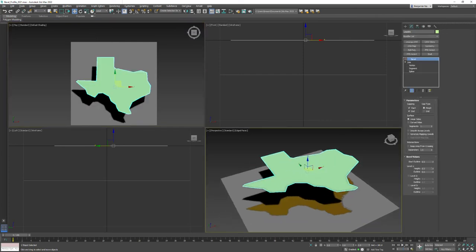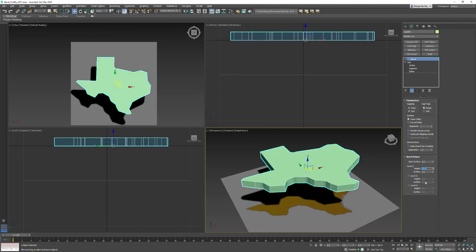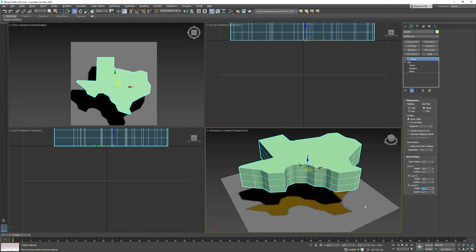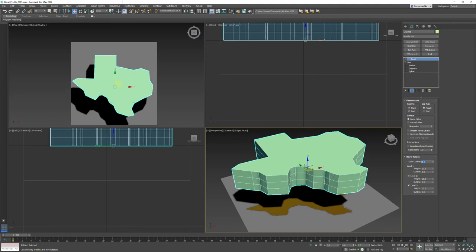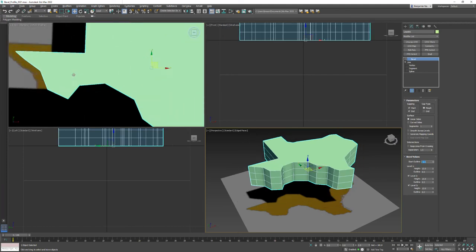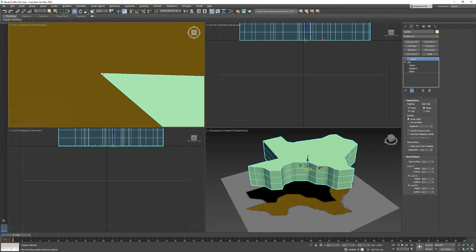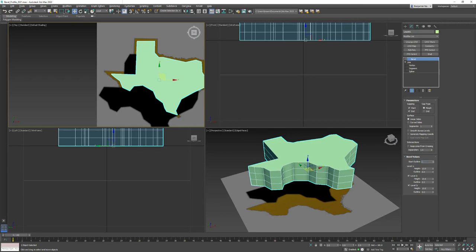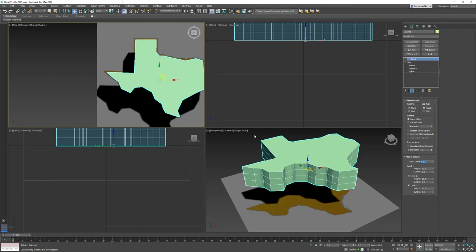Bevel allows you, think of it like this, you have 3 different values, or 3 different types of extrude. So I could say 10, 10, and 10. Now the reason that you have those is because you also have this starting outline. So if I set my starting outline to like 5, you see how everything pushes out. But if I put it to a negative value, like -5, that kind of moves it in. And be careful, if you've got little tiny corners that may cause geometry errors, but maybe I'll just be careful and just do like -2.5. So see how it's a little bit smaller now.